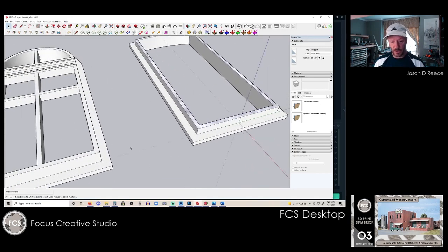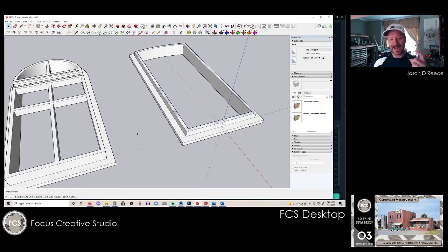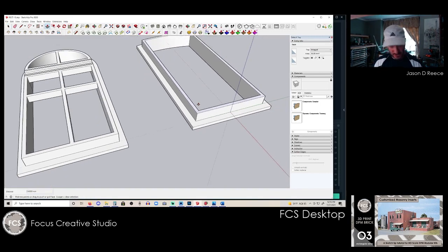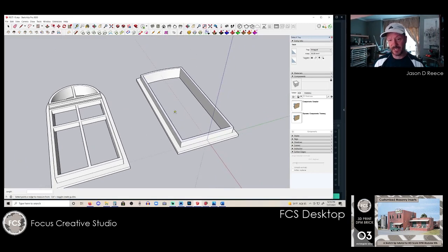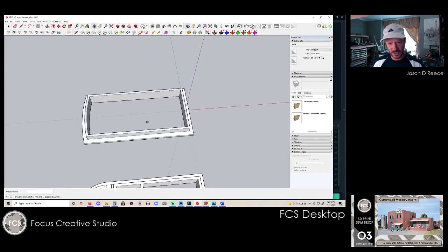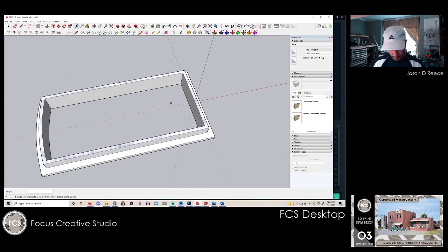So now remember, on the brick pieces, we're adding 0.6 with our brickwork. So we want to go ahead and push pull this frame up 0.6 more. And that'll get us the same as my original 1.6. Yeah, 1.6. So that's basically a perimeter window frame. If you want to do like a picture window, that's it. But we want to bisect this right down the middle, and then we're going to put a horizontal in here as kind of our typical.